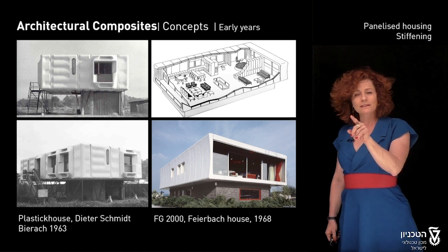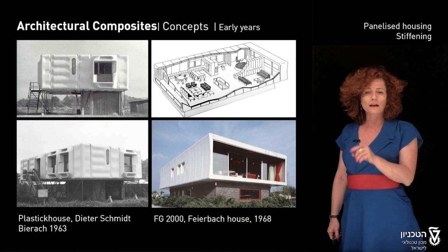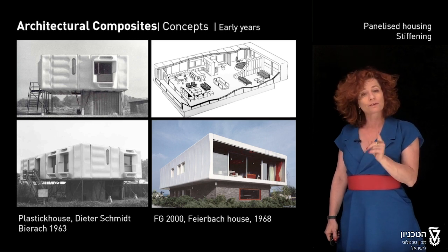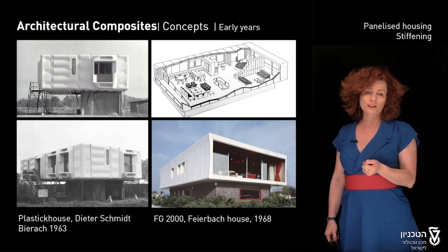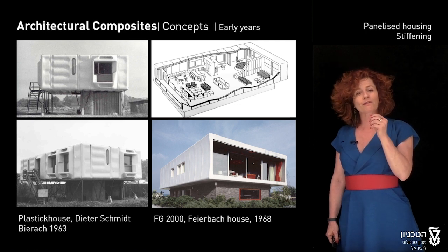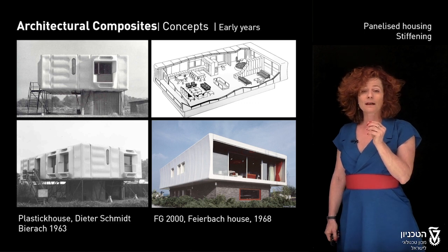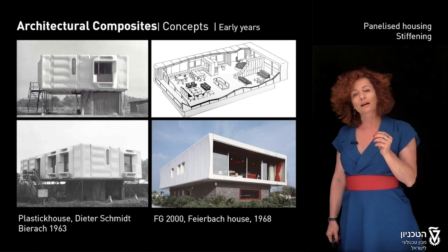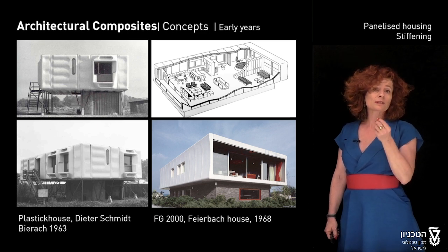Now you see the aesthetics of these two pavilions, these two housing units, and you see the bumping on the left and the curviness on the right. Now there is a reason for that. Since the material is so strong and efficient, well, you don't need a lot of it. It can be very thin. We have very thin layers, very thin membranes or plates. So these membranes, these surfaces, they are strong but not stiff. And for construction, you need to stiffen those.